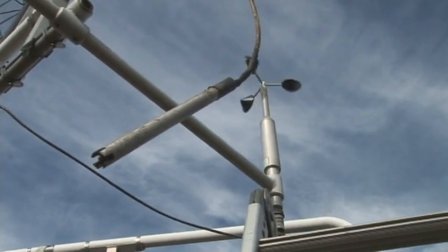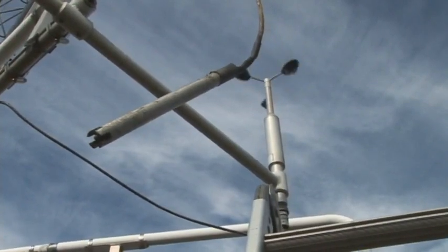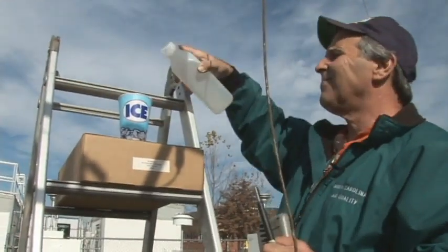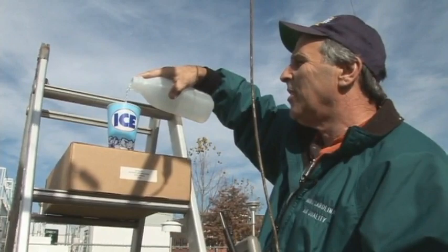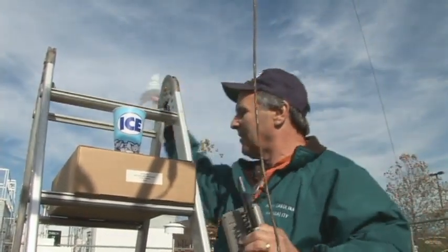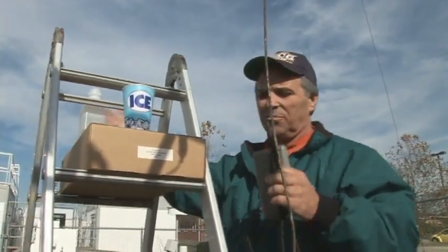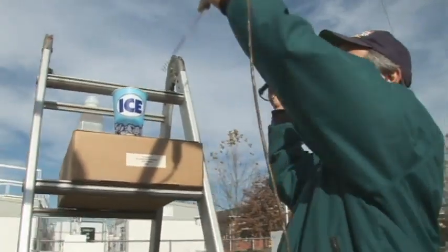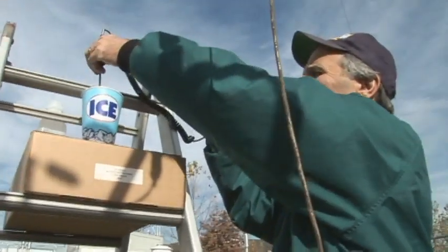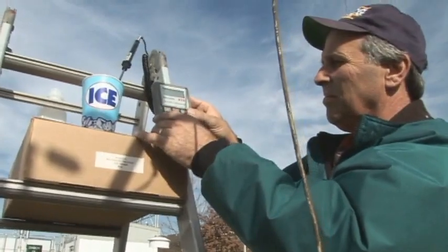Once the probe has been exposed, the outside technician will prepare the first water bath. This is performed by adding ice to water in a container and creating an ice slurry. The best results come when the ice is crushed or broken into small pieces. The probe and the calibration thermometer are now placed in the ice slurry together.